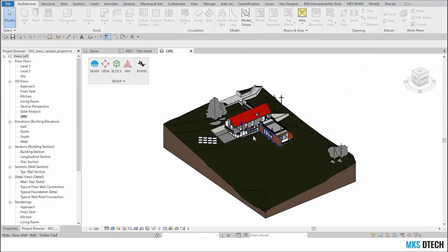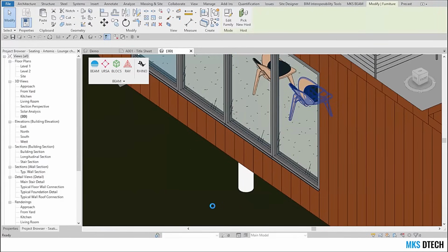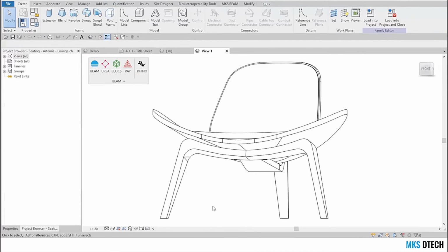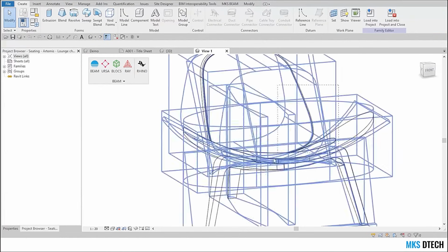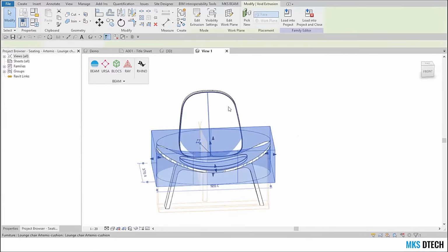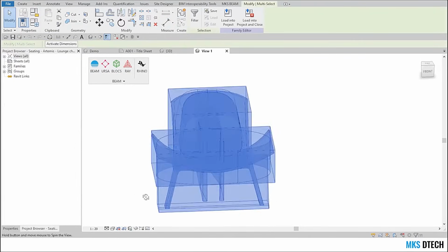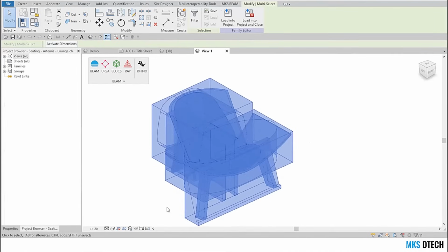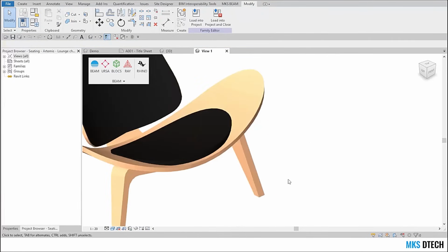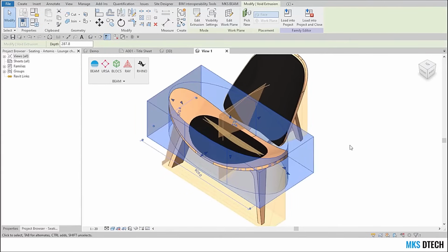If you have a furniture object, let's say this chair coming from the Revit example, modeling this in Rhino is not super difficult, but look what we have to do in Revit to make this family happen. It's a crazy volume, a void extravaganza, to have this chair. This is a bit of a nightmare, to be honest, to manage. And it's a little bit heavier because Revit has to store all the solids before and after the cut, and having this information there makes it heavy.